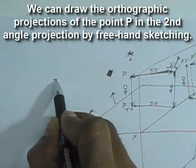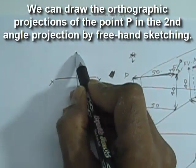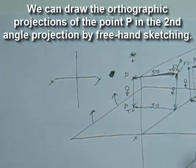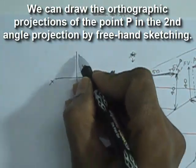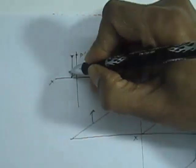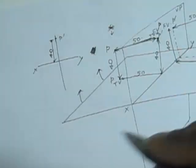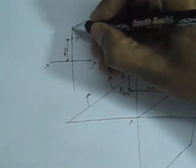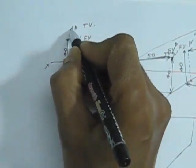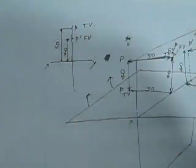So we can draw the orthographic projections in the second angle projection system. Reference line, we draw a vertical line and both the top view and the front view will be above the reference line. So the front view will be at 40 mm above the reference line and the top view will be 50 mm above the reference line, as shown here. So this is the second angle projection system.